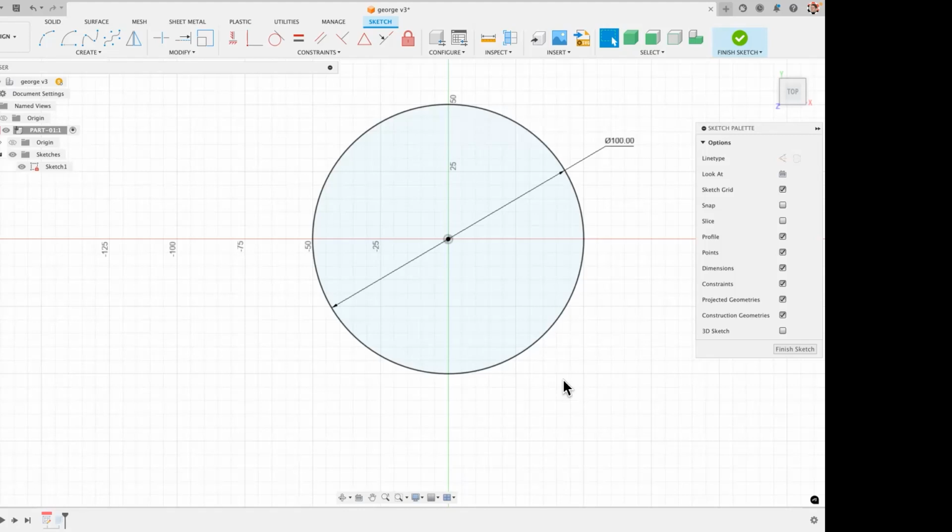So if I click out into nowhere, right? Yep. Okay, my cursor still has a little constraint-like icon. Oh, you have to put down your hammer. Hit escape. Okay, now you just have the arrow, hopefully. Now I just have the arrow. Now hover over the very center point. It'll light up, and do a long click and hold. Okay, so then it gives me sketch point, sketch dimension D3, 0, and profile.